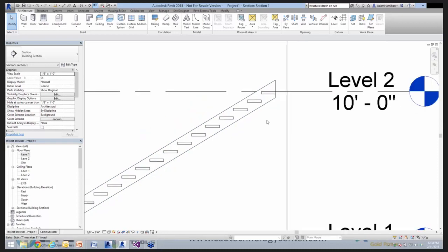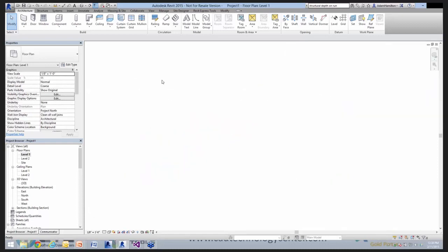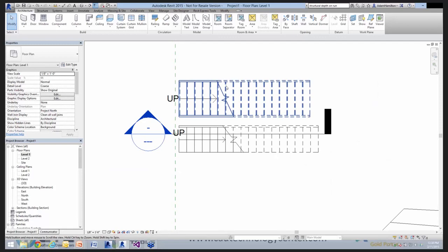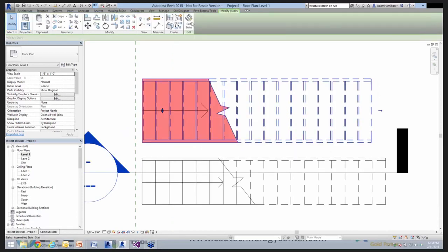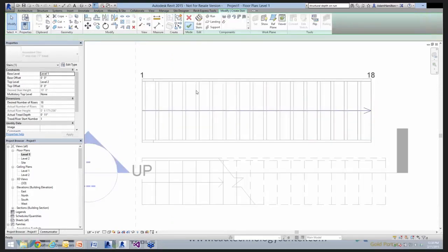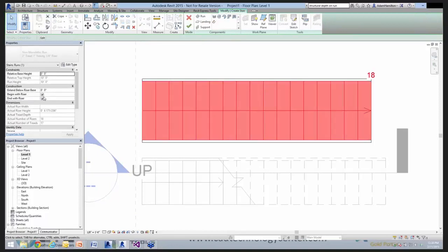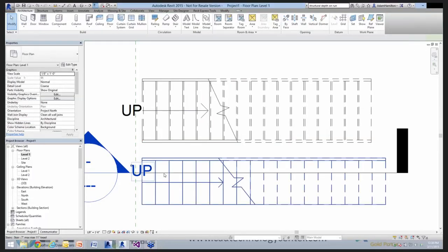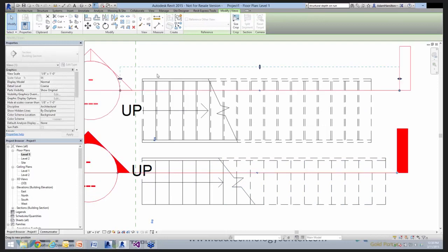Again, you can modify that. It's a hard thing to find, or if you're not looking very hard, on a component stair, when you edit a stair, you have to select the component to be able to get access to the begin with riser or end with riser. You also have this extend below riser base in case you wanted to extend, say, the structure, if you're using concrete or something like that in a monolithic stair, below the floor level.